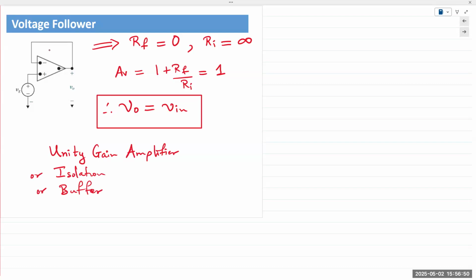Okay. So now let's talk about what's happening in the circuit. We apply an input at the non-inverting terminal. We'd expect it to be amplified. We get some output, right? That output is fed back to the input. The property of the op-amp is that it will try to force both terminals to have the exact same value, Vp equal to Vn. So it will try to force it to go to that value.